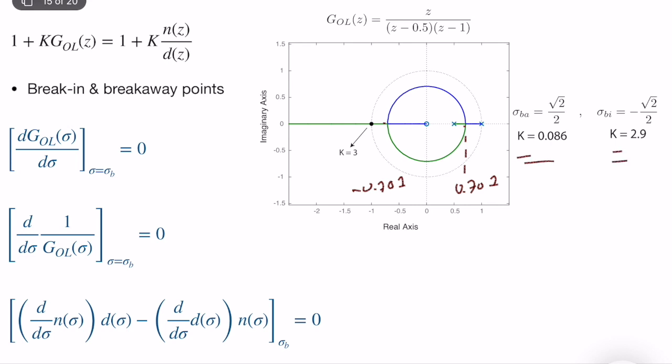So let's analyze this Root-Locus to get a better idea of what's happening. When k is equal to 0, we start at a marginally stable point because we have one pole at z equal to 1. As soon as we increase k from a positive value, it becomes stable. We have two poles on the real axis, so there is no oscillation. It's an overdamped system. That's nice.